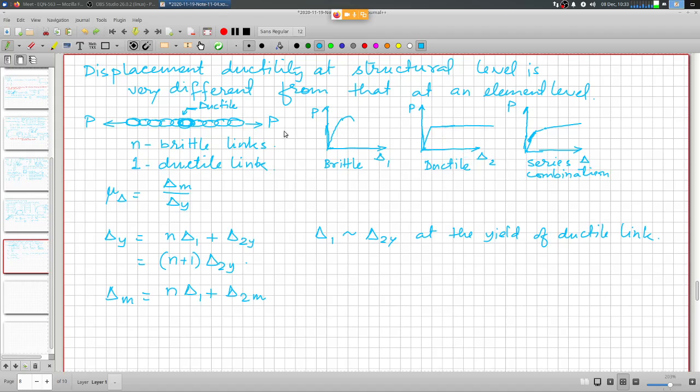If you keep on applying force, this particular element will begin to flow, and the force is not going to be transferred much. The system is not going to take much of the force. So that's why you will see a very, very small slope of bilinear hardening.